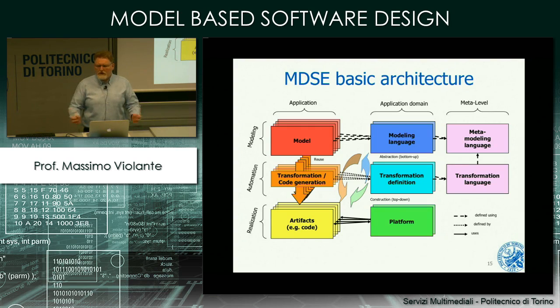Well, one of these blocks is the integrator, 1 over S, okay? That is clearly a mathematical function that we can use for transforming an input signal. Let's say we have an acceleration that is arriving from a certain sensor. We want to compute the velocity, so we integrate the acceleration, okay? So this is part of a control algorithm.